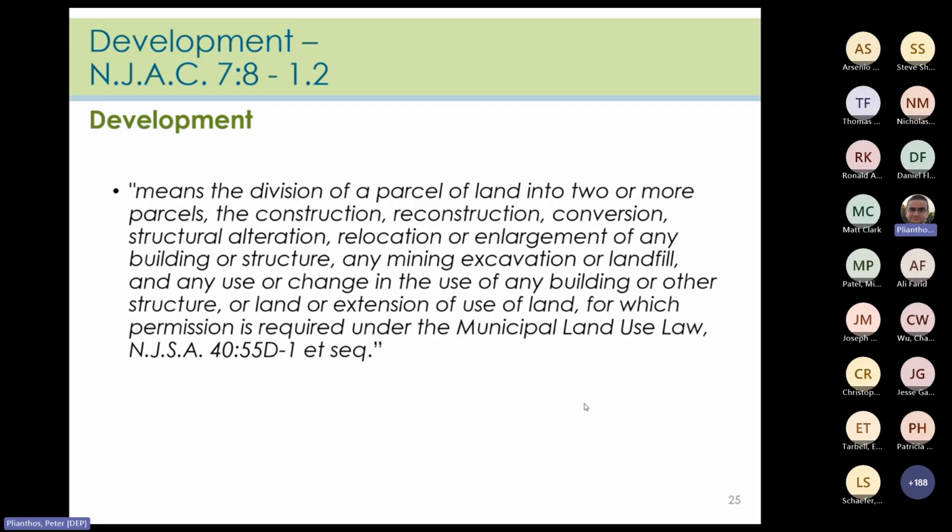If the disturbance, the increase in regulated motor vehicle surface, the increase in regulated impervious surface, or the reconstruction of motor vehicle surface or impervious surface of each individual lot summed together meet the threshold of a major development, the subdivision itself is considered a major development, with each individual lot being subject to the requirements of a major development. The municipality or MS4 permittee must review the proposed development for those subdivided lots as a whole.